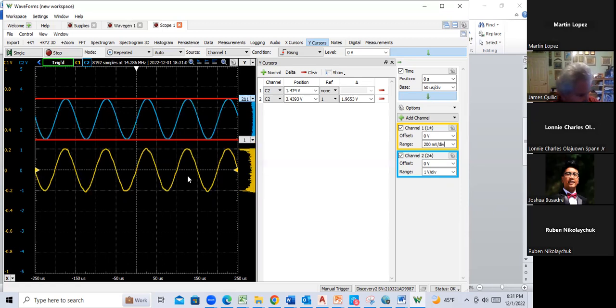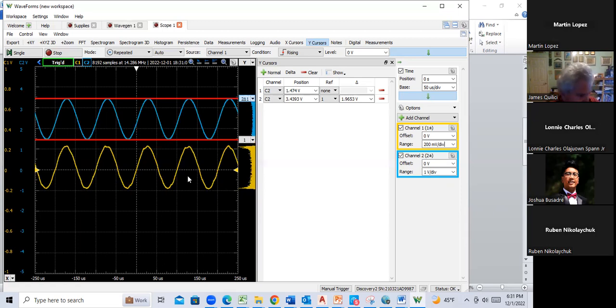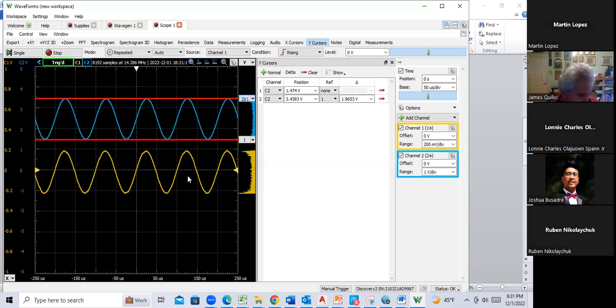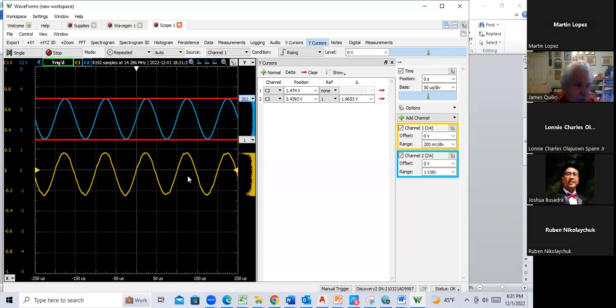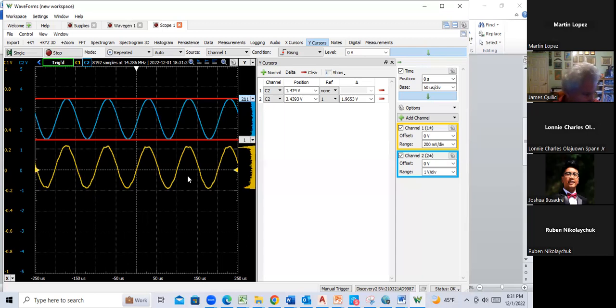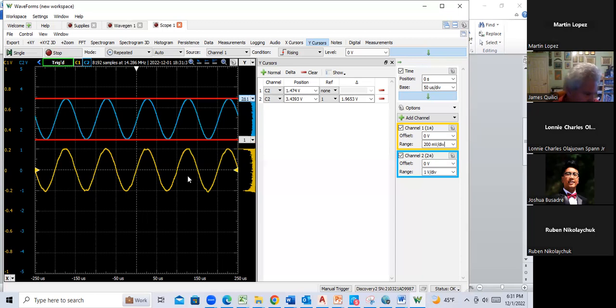Okay, so for step 9, basically run it at 10 kilohertz. You did your simulations last week, and I recall that in the high pass on the AC sweep the dominant pole was the emitter capacitor, and its 3 dB point was in the 400 to 500 hertz range. So if you're running at 10 kilohertz, you're going to be in the pass band.